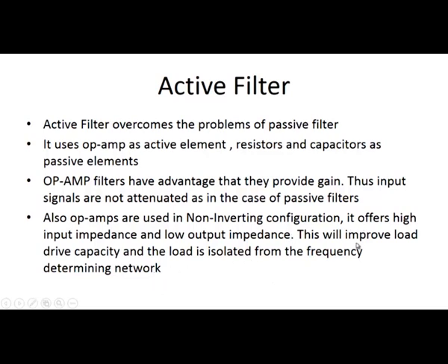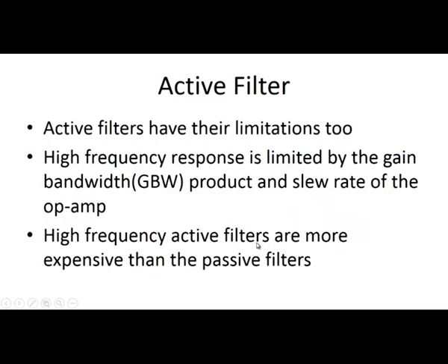We have seen in the previous lectures how the operational amplifier in non-inverting mode has high input impedance and low output impedance. So from that, the active filter, if it has an op-amp in the non-inverting configuration, has high input impedance and low output impedance.